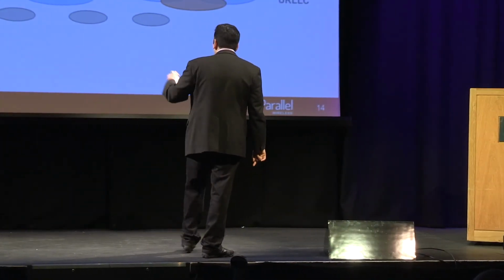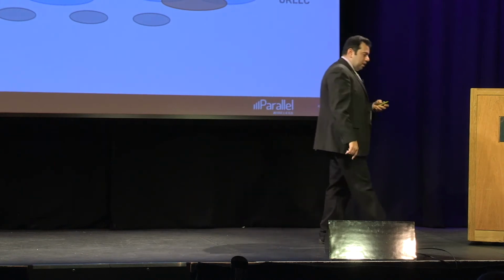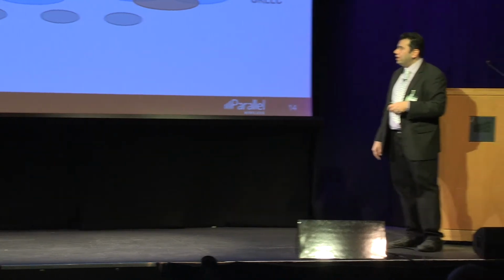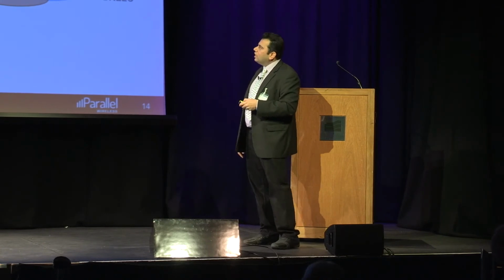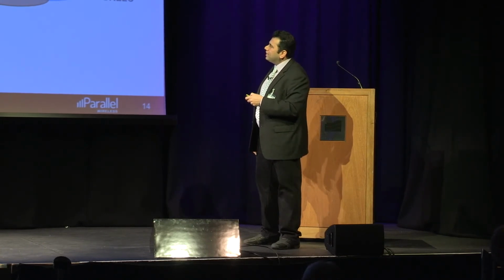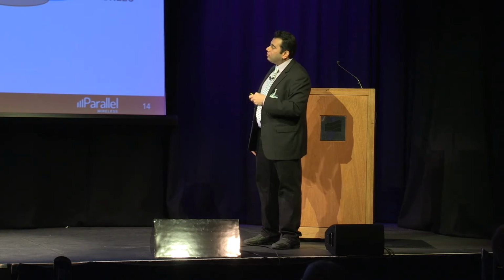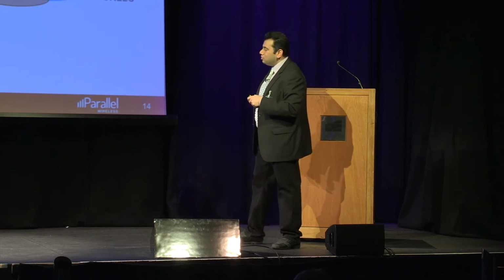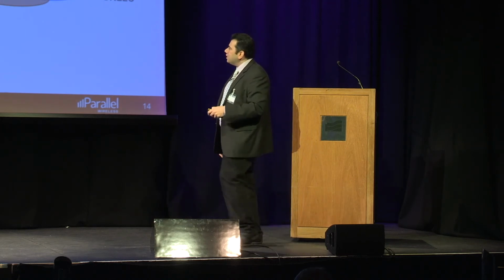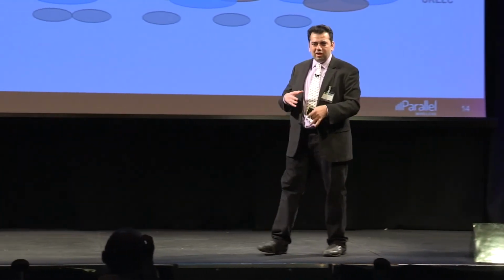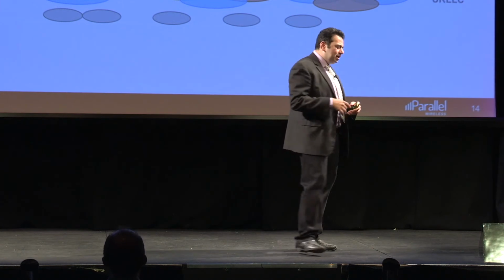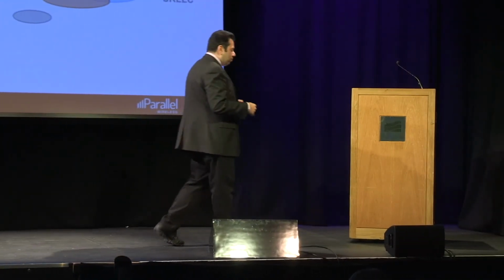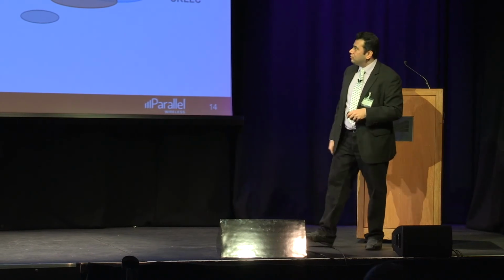So you need the high throughput layer, but because most of the deployments today are what we call non-standalone, we don't really need this. We can get away without having this, but this will become mandatory later on. And again, this has some challenges which need to be solved. So this is the easiest thing. If you want to launch 5G today, just get something in this layer, and the most popular frequency is the C-band, from around 3.4 to 3.8, and I think this is where all the UK operators are going to be doing their 5G networks too.